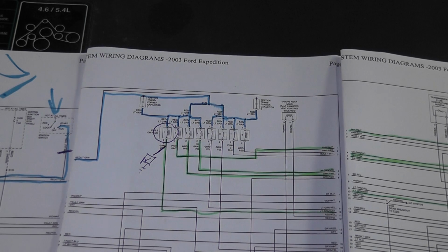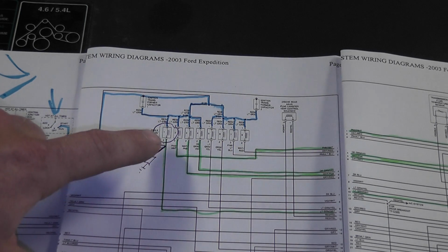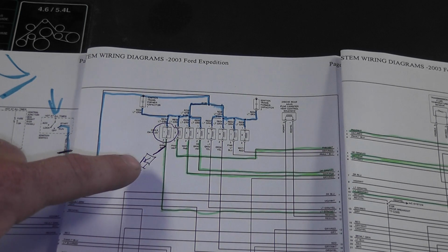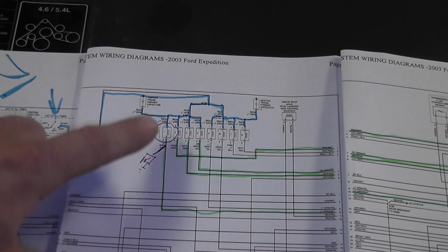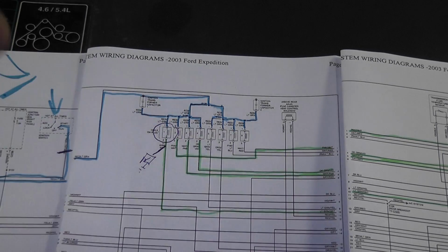We're going to do a voltage waveform on that number 1 cylinder control wire, and so what we'll have is 1 pulse on this signal for every 8 pulses up here, and we'll be able to coordinate them together and take a look at what all of our coils are doing at the same time. So we'll take you up to the board next and show you the waveform. Well, actually, let me get a shot of where we're connected, and then we'll show you what it looks like up on the board.